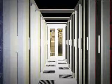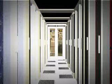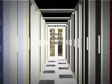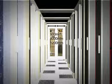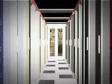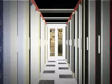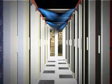Rittal's cold aisle containment system has been designed to be adaptable. The doors at the end of each aisle will fit 900, 1000 and 1200 mm deep enclosures. The roof panels also allow us to adjust the width of the aisle from 1.2 metres to 1.8 metres. The inclusion of a 100mm plenum, which increases the roof height, not only allows us to provide additional headroom, but provides important space for additional features, such as security webcams and fire extinguisher systems.